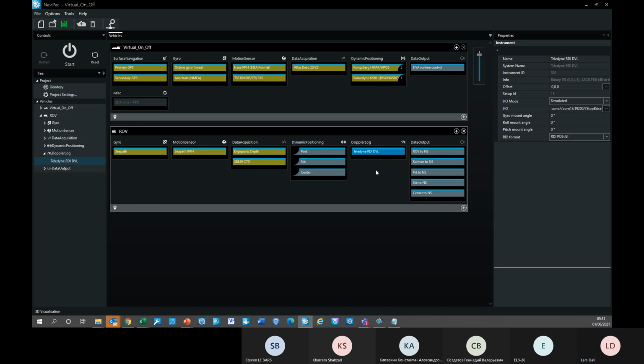and right. And then it is measuring the Doppler shift, that is the change of frequency of the returning signal, or rather the returning signals in the 4 directions. And based on that, it can calculate the speed in these 4 directions. And then again, based on that, it can calculate the speed and direction of the object in question that is carrying the DVL.